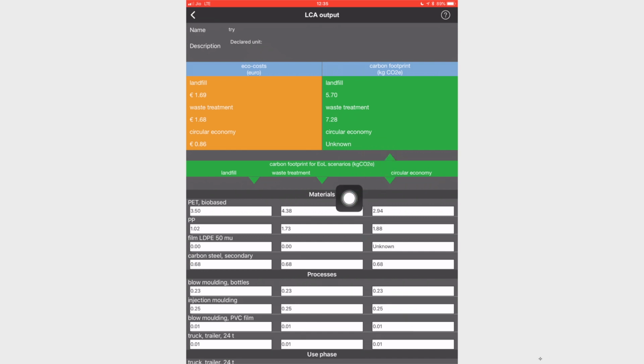As we already discussed, if I replace polyethylene with PET, the weights do not remain the same any longer, because of the cross sectional differences in density. So say the total weight of the product will now be 10 grams rather than what we started with, 1 gram. A part of this will be used to make the bottle. So let's say half of it is used for making the bottle, so I put that in blow molding, and half of it will be used for making the cap. So I put that in injection molding.